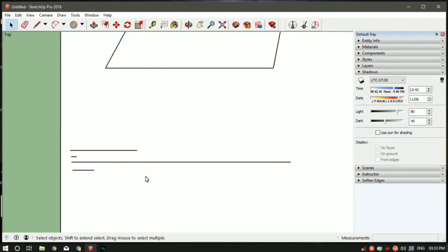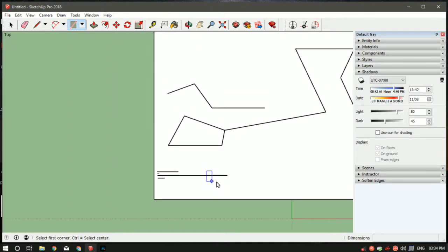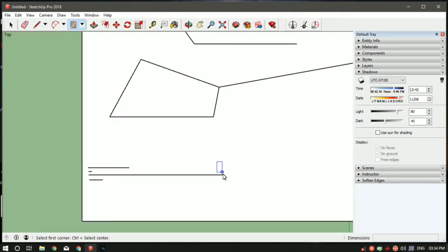Let me jump into the rectangle tool. It's in the top ribbon, in the shapes command. Just left click on this arrow and you can select the rectangle, or the shortcut is R. So basically two options are available in the rectangle. One is the corner rectangle and the second one is the center rectangle. What I mean by that is, let's say I want to make a rectangle whose one of the vertices is this point. So just left click to select that point and then give the X coordinate and the Y coordinate.